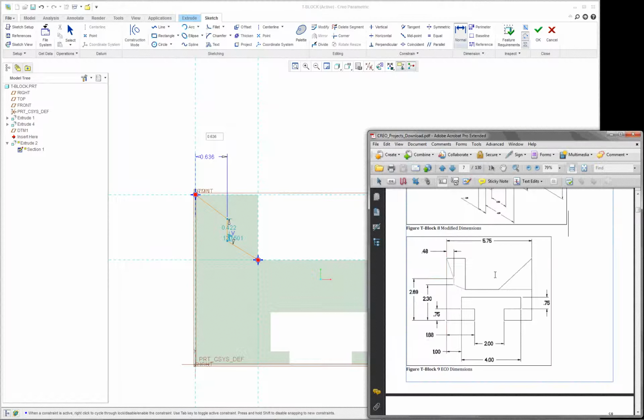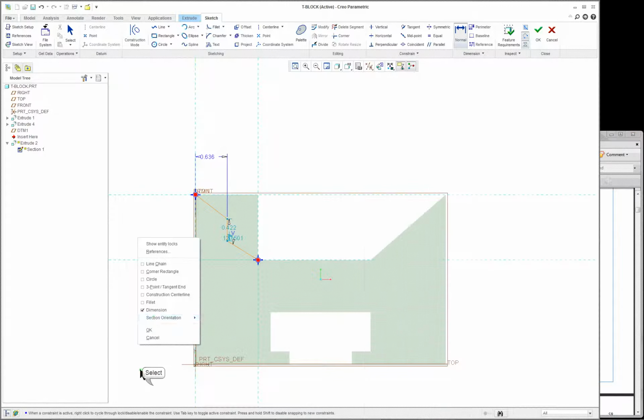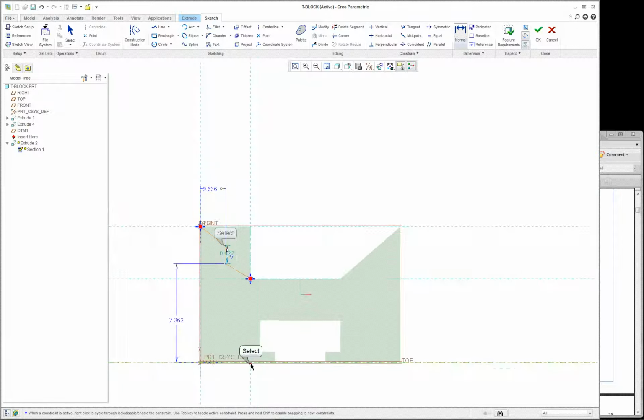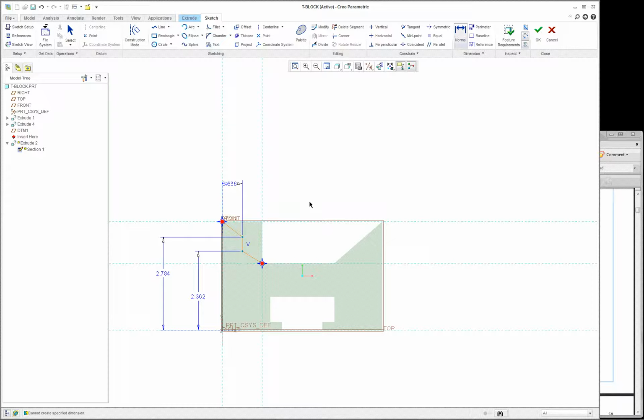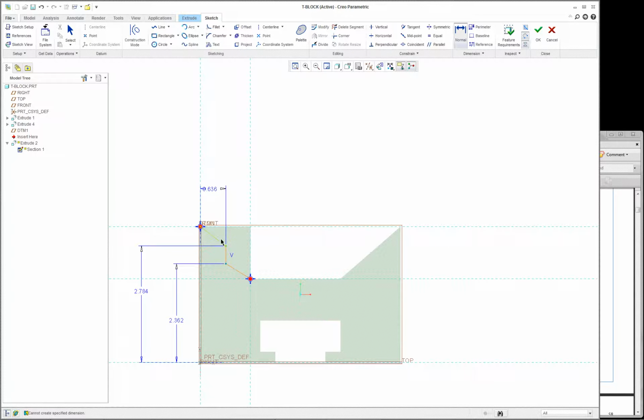And if you look over here, you've got to use these dimensions. So I'm going to come from here up to this point, and from here up to this point. Oh, didn't get it. Dimension still selected. Reference to point, middle mouse button, and we've established the new cut.